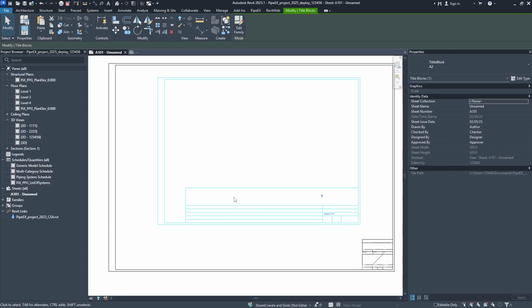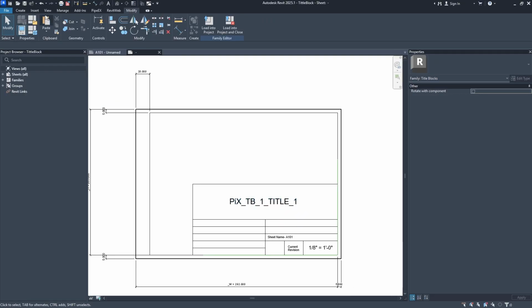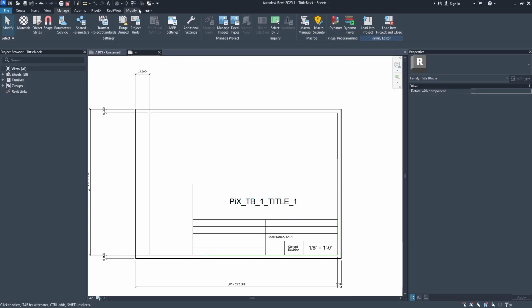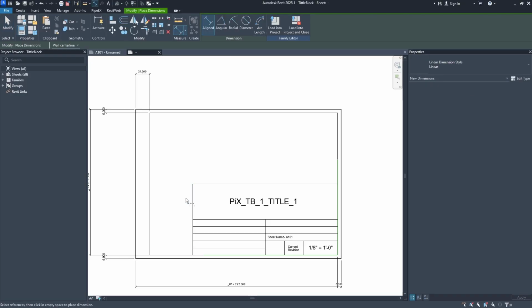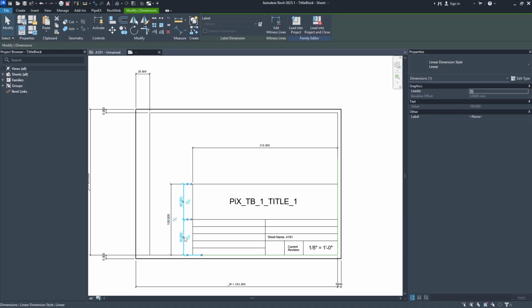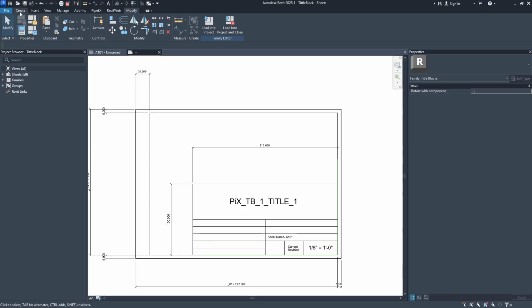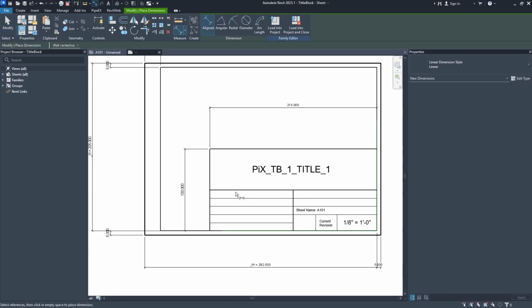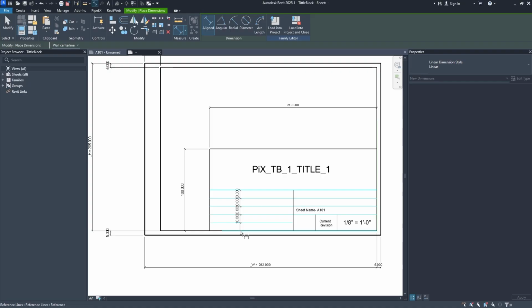As you can see here, already something is not right, because we did not lock all the lines that we have added. Sure, we also need to lock them to protect from movement. This is what I'm going to do now. Of course, it will not allow me to do this dimension, but for this one, for sure, I can create it.